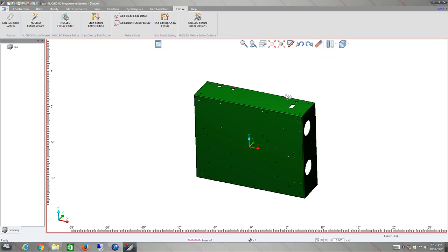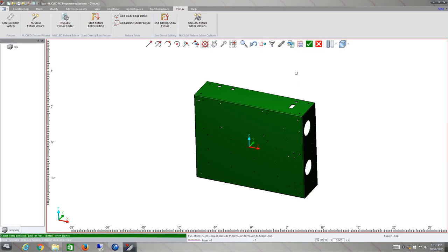One thing to remember when you're using the software, you may sometimes need to manipulate the view. So for instance, if I wanted to delete this box, I could click the delete icon, and it's prompting me for the items to pick in 2 places. What I might want to do is get to a component or an entity on the back side of this box, but I can't see it right now. So the little shortcut to get around that problem is to keep the shift key down.